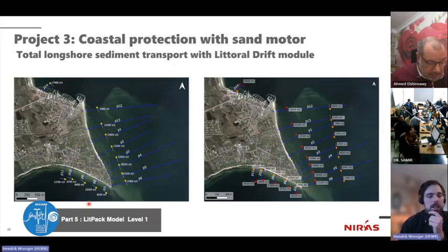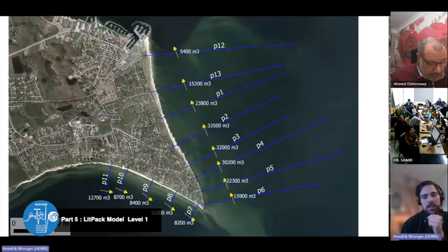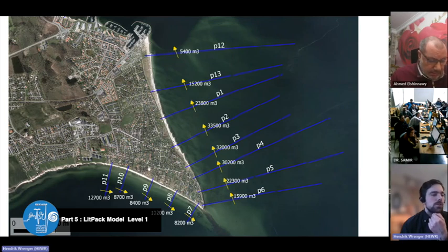And then we did not use the coastline evolution module. And why did we not use it? Well, we could have set it up maybe in two sections, but clearly you cannot model the transport along this headland. There's a bar underwater extending. You have some opportunities to model local structures, like the local interruption or the local effects on longshore transport in the coastline evolution module, but certainly not outside the box where the coastline overall follows a baseline.